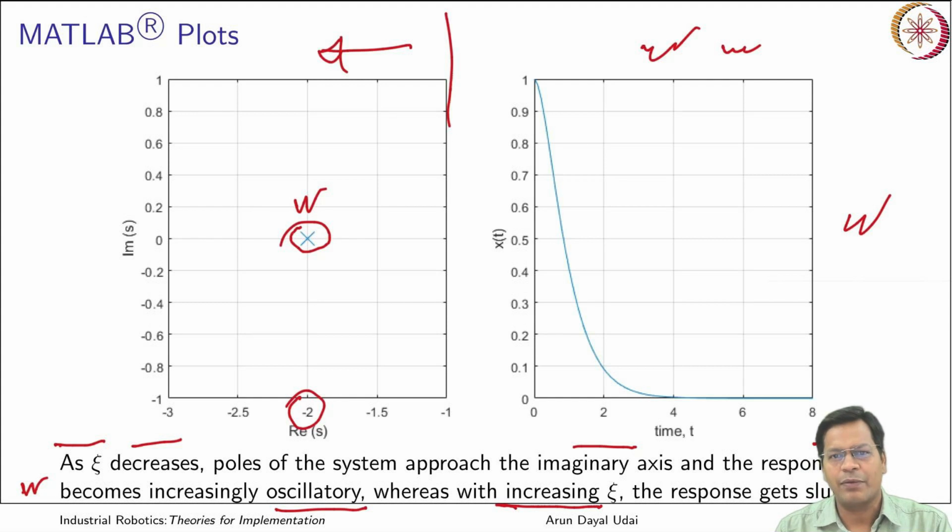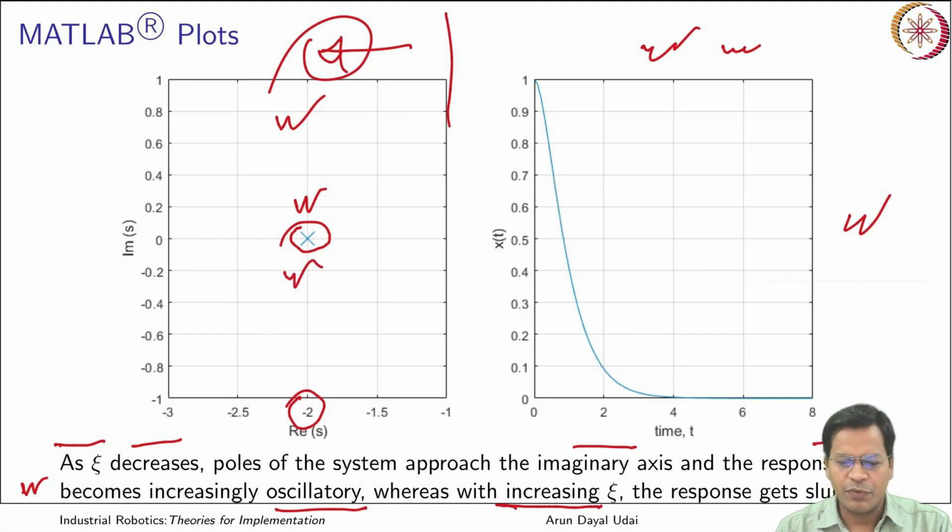In all these cases I have given some examples to make you understand. So you just have to remember where in a second order system those roots should lie. Okay, so they should lie in the left half side of the plane, and preferably we would prefer to get this, but if not this, you should be happy with the critically damped case, or you would be better off having an over damped case, but definitely not an oscillatory nature. And pure oscillation is definitely very, very bad. Okay, so it will keep on oscillating infinitely. So those are the undesirable cases.